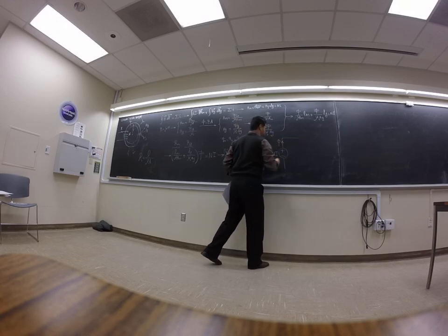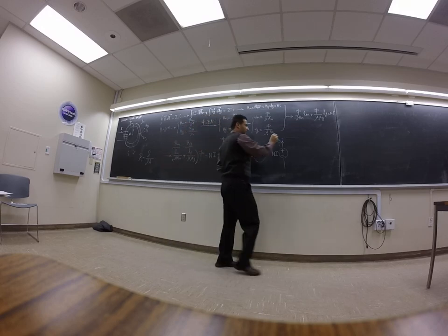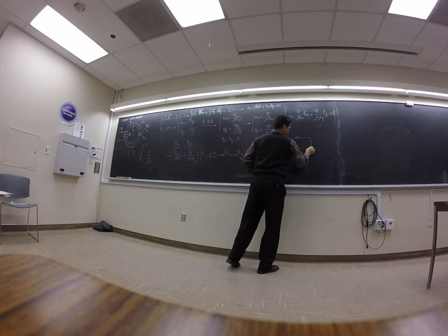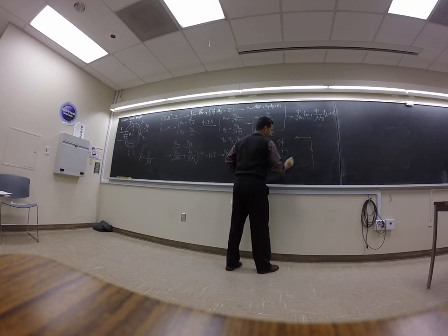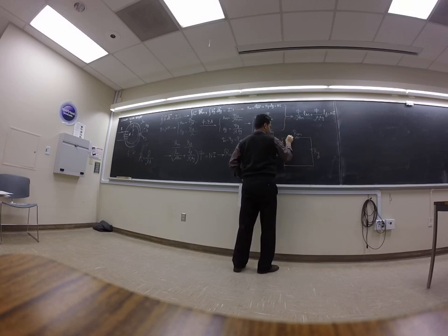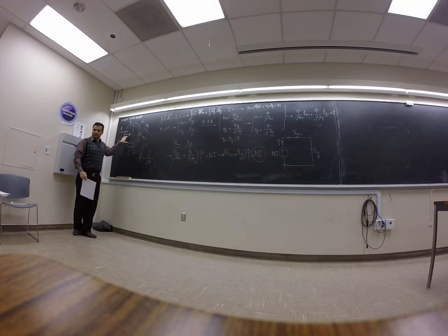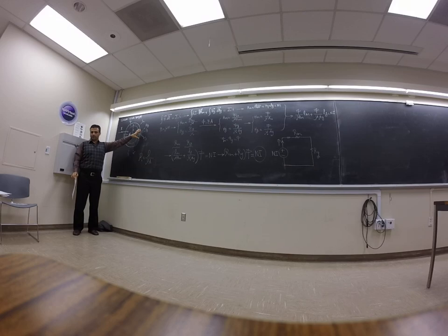The next one, we are going to have one magnetic resistance for the core, one magnetic resistance for the air gap. So it's going to be like this. This is the equivalent circuit of this. So basically, when we have two materials, you put two resistors.